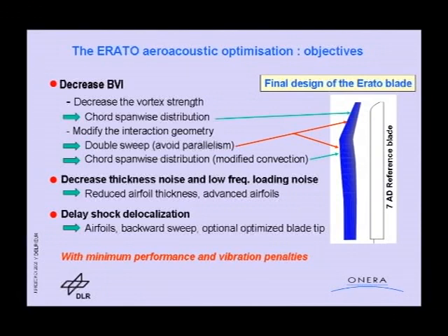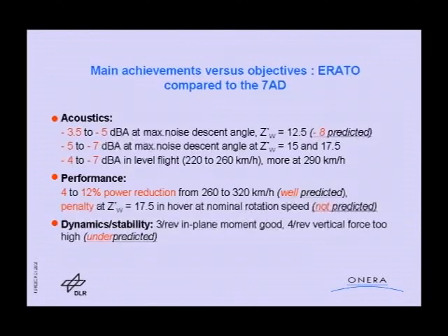And in addition, we wanted to decrease thickness noise and low frequency loading noise by reduced airfoil thickness, advanced airfoils, and delay shock delocalization using advanced airfoils, and the backward sweep was beneficial. And all this with minimum performance and vibration penalties. And these are the results that we obtained.